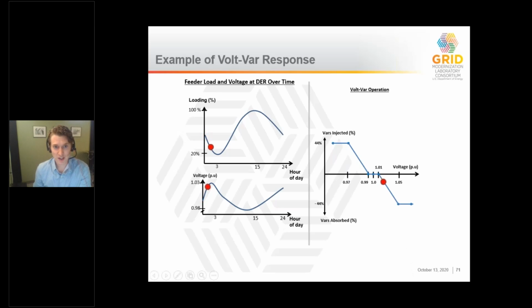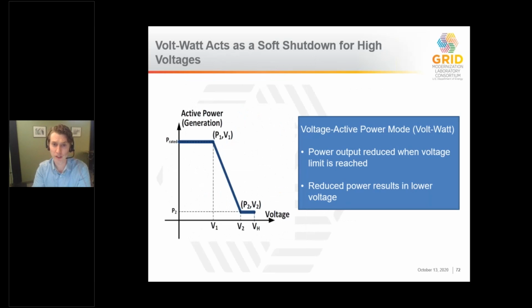So as we see, the voltage is high and we were absorbing current briefly, voltage goes low and we're injecting reactive current. That's basically the operation of the volt var curve. It's going to sit there constantly monitoring the voltage and react with current over time. Next slide, please. We'll play it one more time in case you didn't catch it. So it's responding with a 5-second open loop response time. So it's not extremely fast, but it will help manage voltage, at least locally.